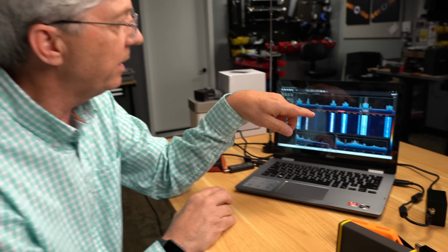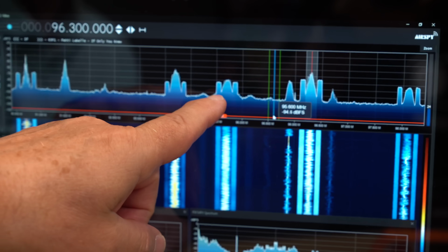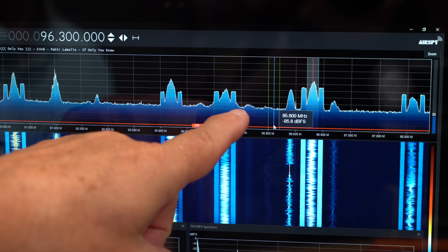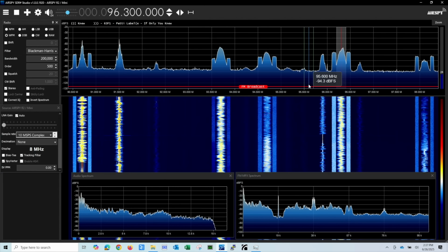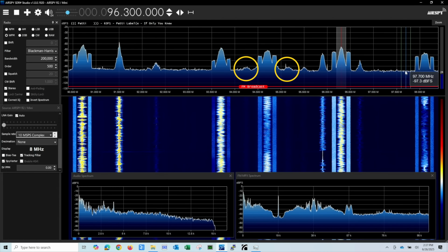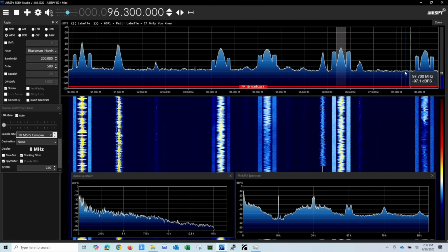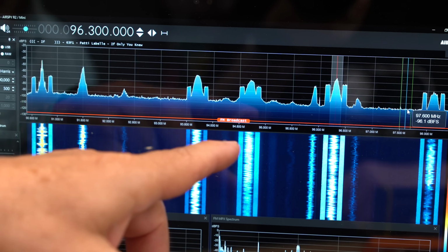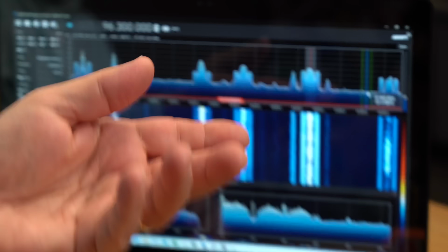And then here, see, this is like a little HD, a little bit of regrowth. It's on both sides. It looks like their transmitter is not suppressing the regrowth too well today. So that's kind of an interesting thing. These are things where, as an engineer, I would call the guy at that station and say, hey, I'm seeing this. Are you too, on your $10,000 piece of gear, right?